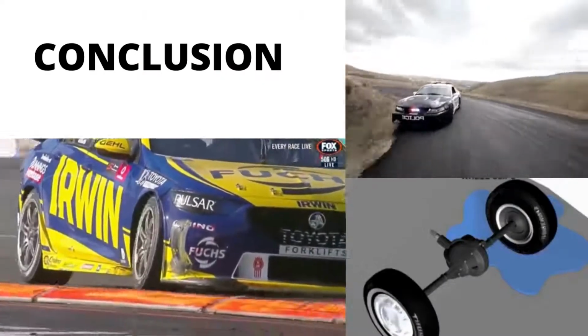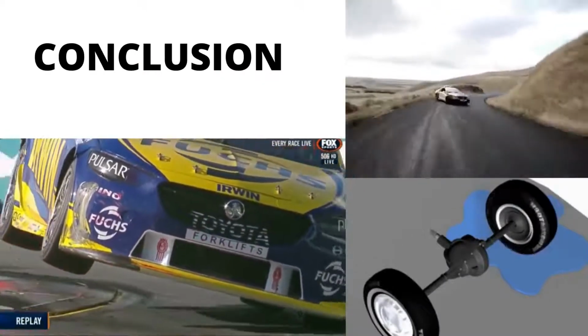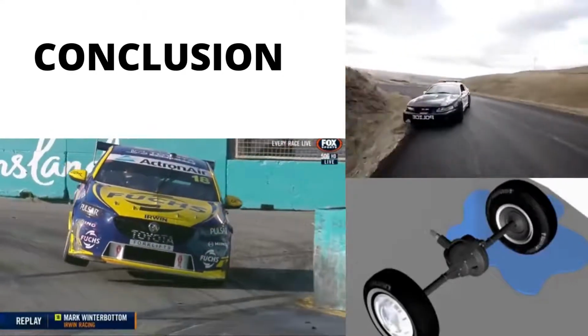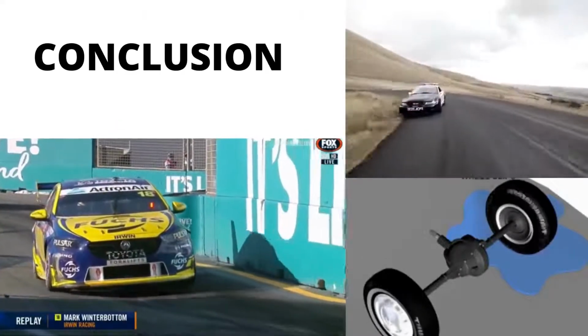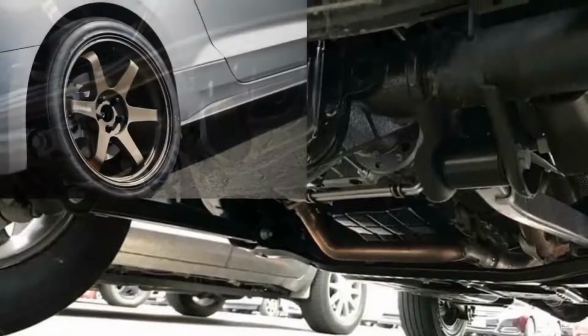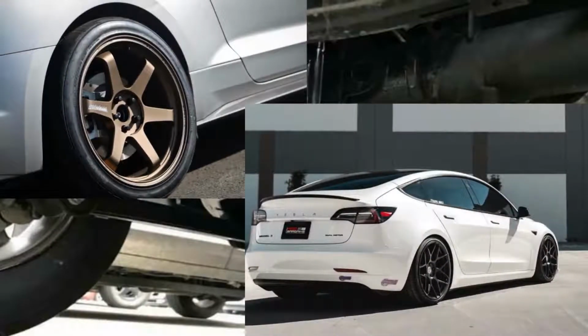As a conclusion, limited slip differentials give a lot of benefits to drivers. One of them is that LSDs allow drivers to put down as much power as possible without breaking traction. This means that the car can corner faster without the unnerving feeling of tires losing grip. It also means less wear on tires due to loss of traction. In a rear-wheel drive car, an LSD can prevent oversteer by mitigating a loss of grip during hard cornering.